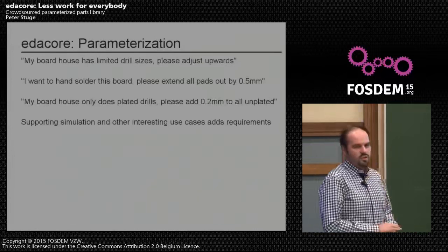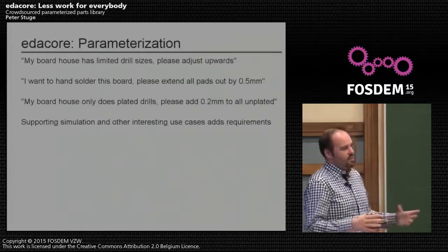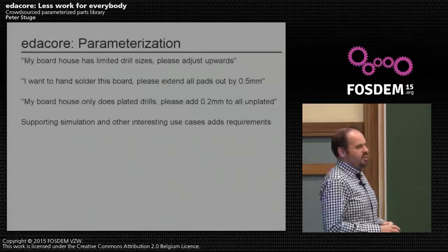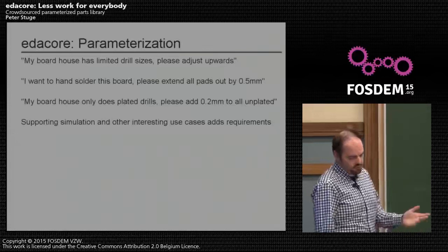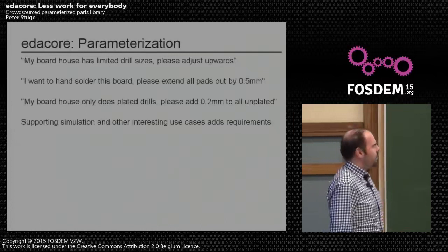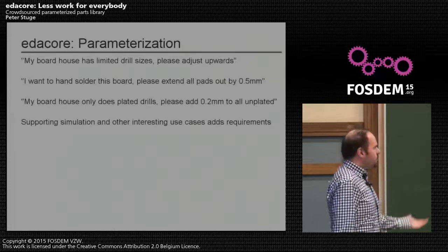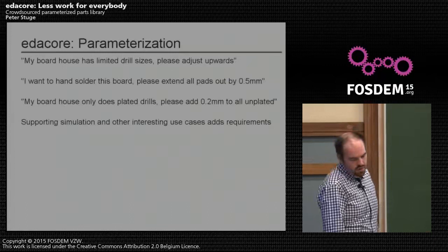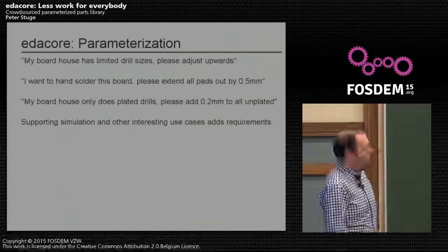I want to hand solder this board, so please extend all the pads outward to the packages so that I have a bit more space to work with. But this only applies to the footprint, and I don't want to make a whole copy of the footprint and mess around with that and keep two of them. It should all be associated to this one part. And simulation and other use cases will add more requirements, but also more possibilities.